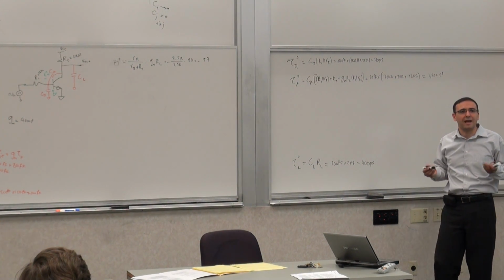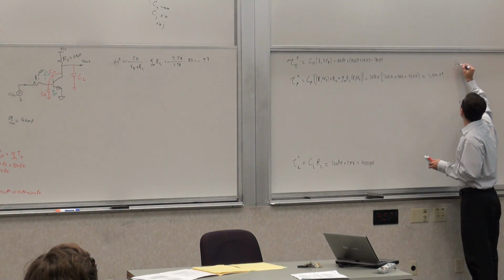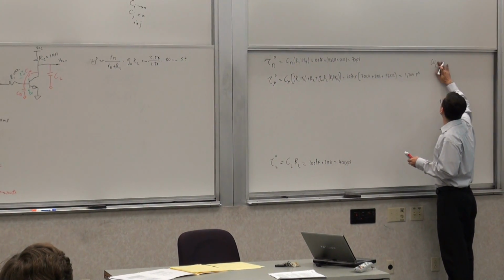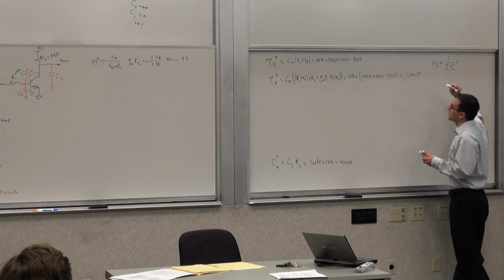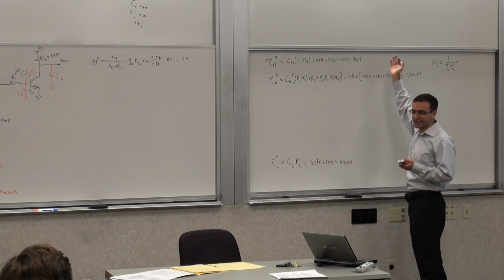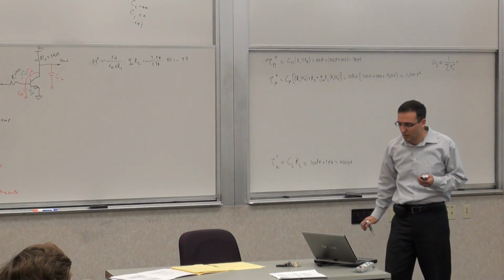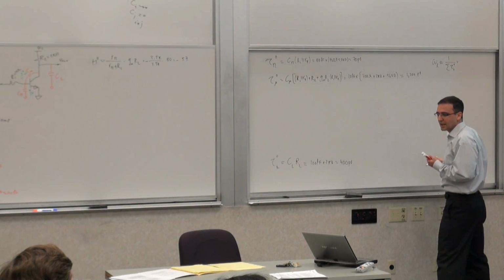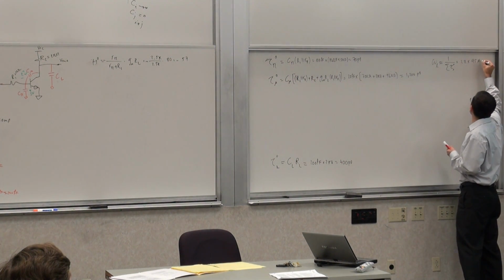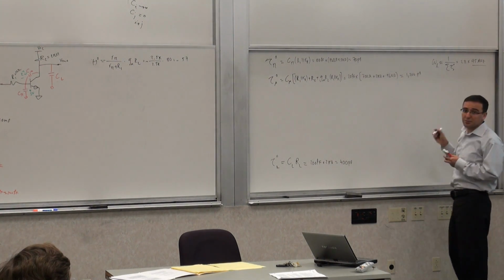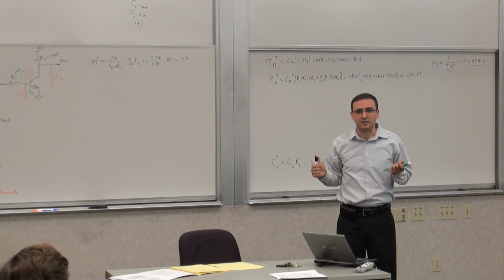Now, let's estimate the bandwidth. Let's see where the bandwidth is. So omega L is approximated as 1 over the sum of the time constants. So you have 1600 and change. If you calculate all of these and add them up, you're looking at 2 pi times 95 megahertz. So your estimated 3 dB bandwidth based on this method is 95 megahertz.